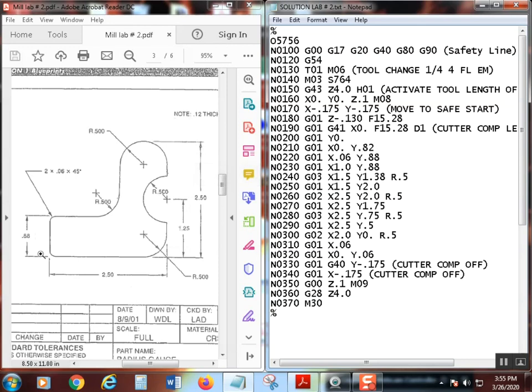So we're going to call this again. Let's go ahead and number our points. So Y0 is going to be 0.1. I'll do that now. Okay. So it's going to go to there. Then it's going to go up to here. Now, like I said, this is a chamfer, so we're at X0, but we're 60 thousandths down in Y. So 880 minus 60 is 820. All right, so that's 0.2. So we're moving straight line, 0.2, G01.